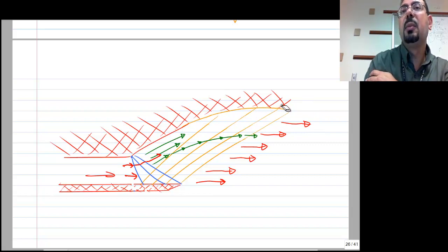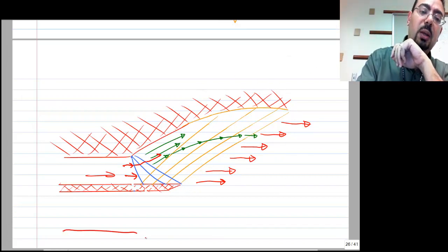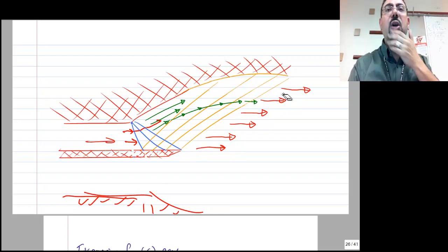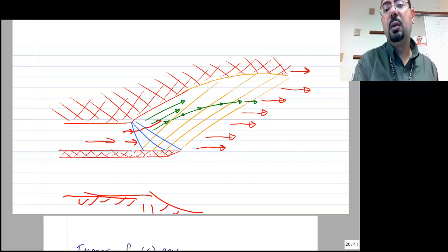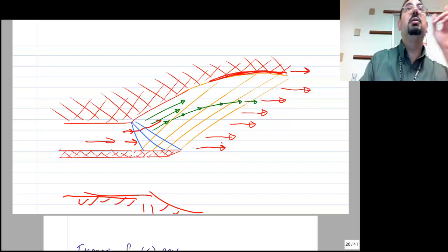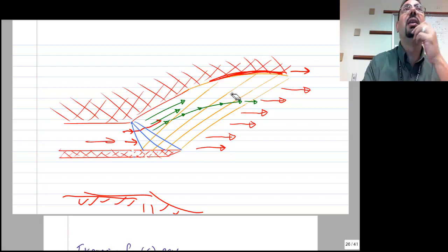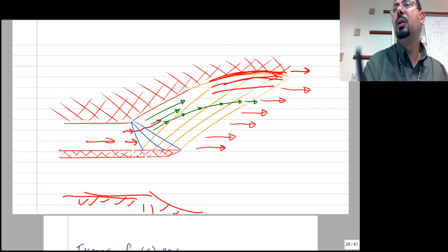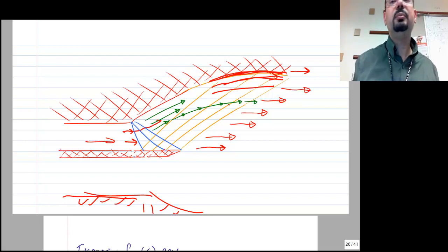Alright? So to kill the reflection from the top, what do you need? Because this is as if you are designing a rocket nozzle. Okay? This part is really as if you are designing the exit of the rocket nozzle. So in order to prevent any reflection from here, what do I need to do with that wall? It finishes horizontal, that's correct. But here, and gradually, it should basically be matching this, right? It should match this so that when the ray comes here, there is no reason for it to reflect, because the flow next to it is just exactly like the wall. So that nozzle basically just goes with the contour of the flow field. You got it? Yeah.